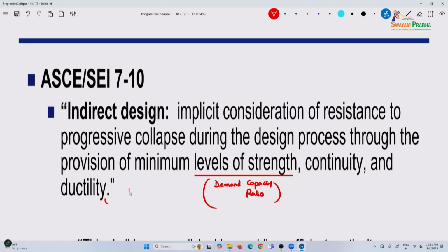So, ductility is again ensuring, for example, if you are using steel, this is F sub y and F sub u, at least 25% increase, and you can have limits on how much extra ductility should be provided. So, those kinds of steels should be used.